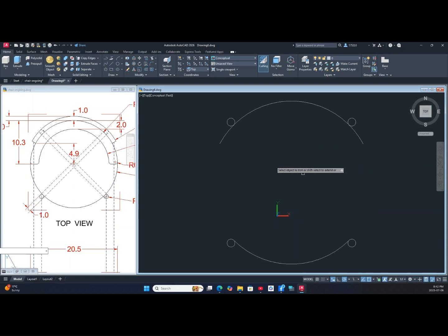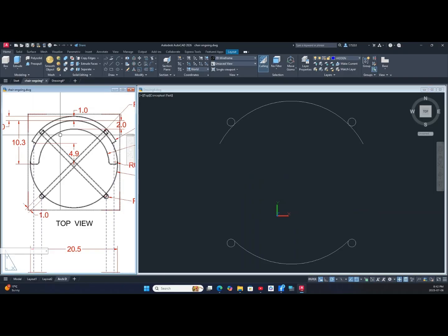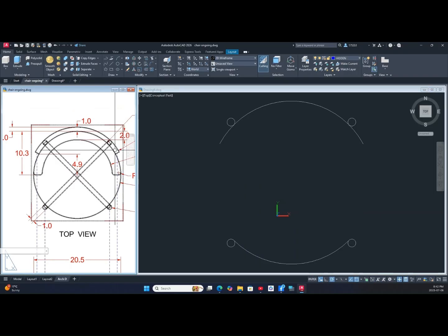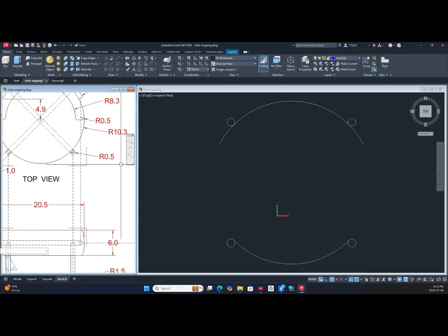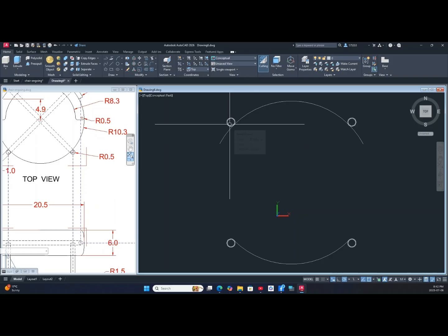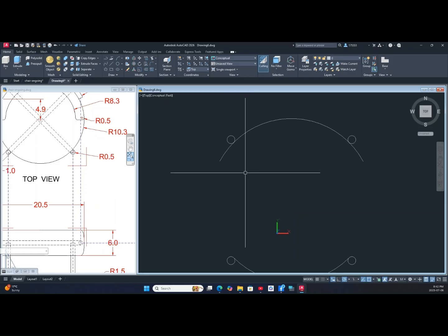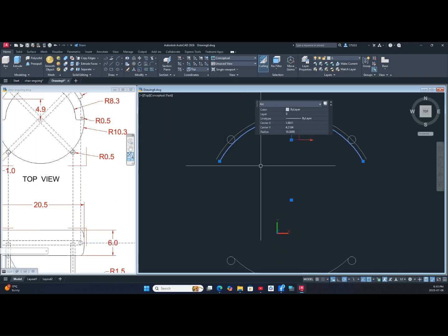And escape. Now, as you can see, the radius for the rod is 0.5. So I'm just gonna put it here in the middle of this circle. So I'm gonna offset this one for 0.5 because that's the radius. Okay, O for offset and enter 0.5. Yeah, because the complete distance from here to here is 1. So 0.5 to put it in the middle. There you go.